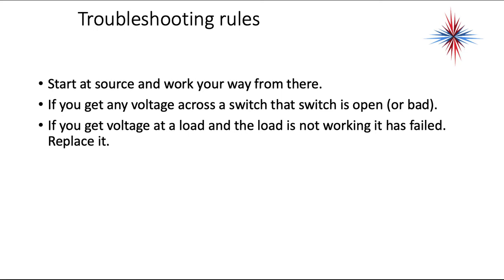Some general troubleshooting rules: start at the source and work your way from there. If you get any voltage across a switch, that switch is open. If you get voltage at a load and the load is not working, the load has failed.